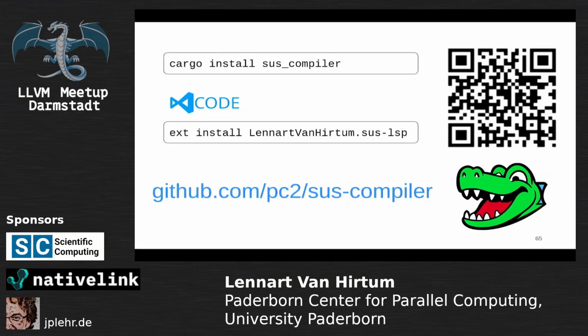You mean dynamic scheduling? Yes. In SUS, we only do static scheduling through the latency counting system. For dynamic scheduling, you would have to declare a multi-interface module, where you have an input interface where you say, okay, start the module, and you need to have that extra control wire to tell it to start, of course. And then you will have what I call a trigger, where the module will then trigger the output through one of its interfaces that says, okay, the computation is done. Here is the result.